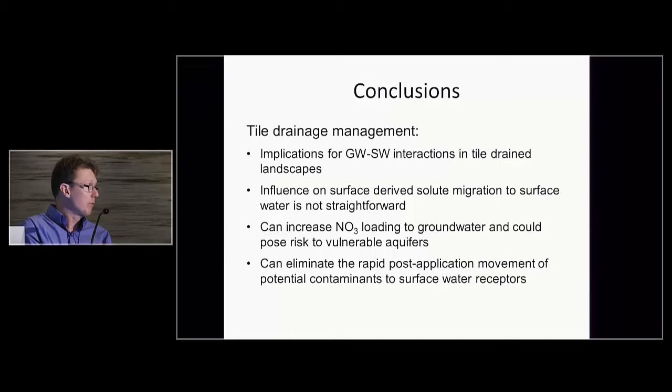And while this talk focused a lot on nitrate and the dye tracer, for certain, under all scenarios, we noticed that controlled tile drainage was able to reduce bacteria and pathogen loading to surface water. So even though the concentrations for the solutes came up a little bit for controlled drainage, the bacteria and the pathogen concentrations were actually in line with what we observed at free drainage, and because of the lower flows, we had lower bacteria loading.